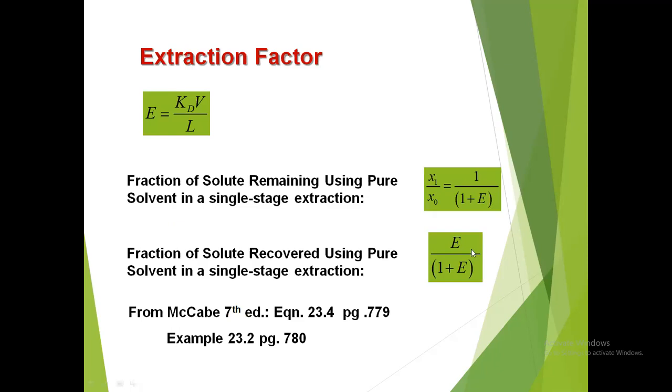Now, this is the last part of extraction actually, and this is the easiest part. That is why I place it in the last part. This allows you to use the extraction factor, given here is the formula, in determining the fraction of the solute remaining in your feed using pure solvent in single stage extraction.